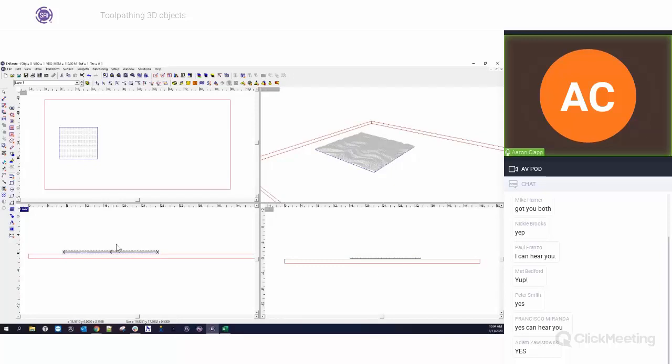So depending on what you're doing, this will sometimes throw you for a loop if you try and move it. Sometimes you'll get a scenario where the toolpath is left hanging up in the air, but the relief got moved down. So just be aware of that. That could be a possibility. That is why our recommendation is to do this as a habit. Always move your material, the 3D object that you're trying to cut, into the plate first before you go and cut your object.